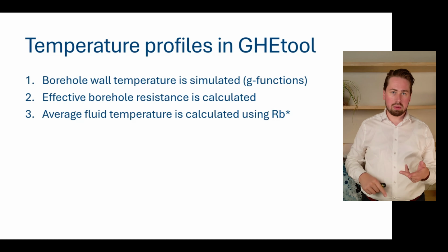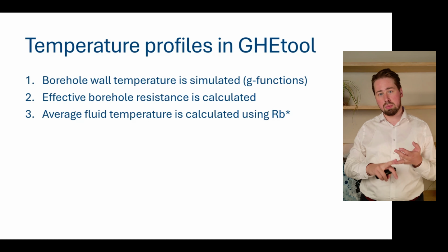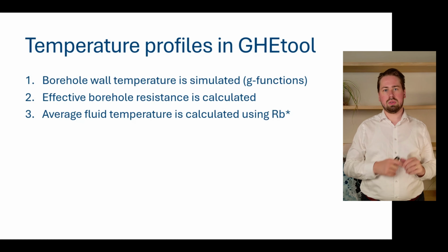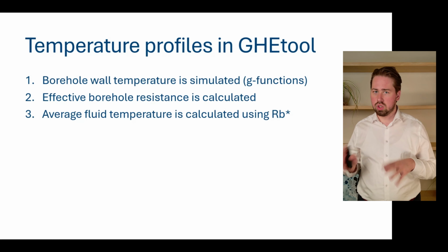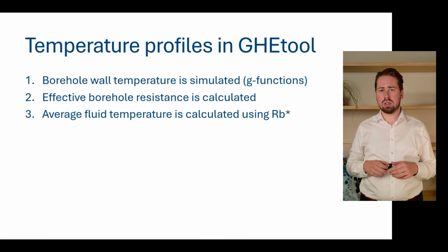And since we know the power, the borehole wall temperature and the borehole resistance, we also know the average fluid temperature.